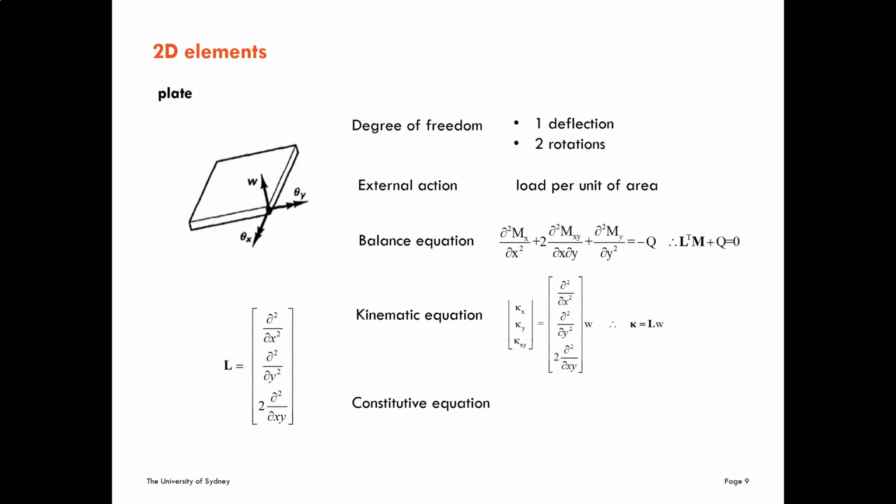And the constitutive equations are similar to the one in the beam, but it is going to be 3 by 3 because we need to relate 3 curvatures with 3 moments. So here you are going to have a matrix in terms of the Young modulus, the Poisson ratio, and the thickness of this plate. So these are the governing equations of the plate element.